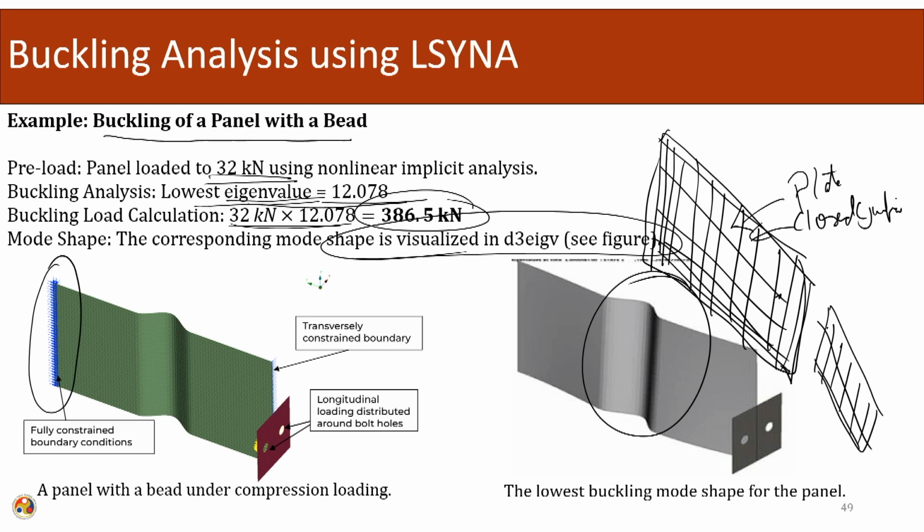Now we can click on each part, and each part will behave as a plate, but they are interconnected. Once we have done that, we will tell it what type of sections we want it to follow. There are different plate formulations, so depending upon our usage, we can give the appropriate plate formulation.